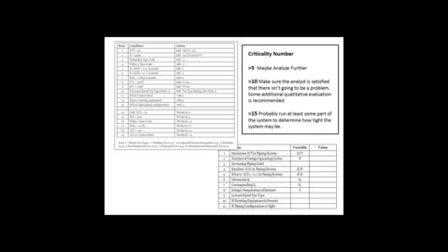If the number is greater than 5, then maybe we need more advanced analysis. If the number is greater than 10, then we probably want to look at the SIFs and the Ks that we have and see how accurate our existing calculation is for them. And then if the criticality count is greater than 15, we probably want to run FEA tools on that system.